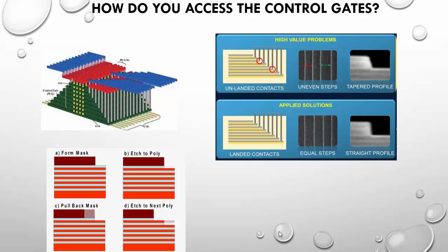Finally, a very thick silicon dioxide layer is deposited on top of the entire staircase, and another pattern is lithographically created for the wires, and the trenches are etched down to the polysilicon layer. The etch is controlled to remove only the silicon dioxide, so each trench stops when the polysilicon is reached. The wires are then filled with the conductive material, tungsten or polysilicon, to bring the control gate connections, or word lines, to the top of the chip, where they can be routed to other wires that connect them back down to the CMOS logic on the substrate that drives the array.